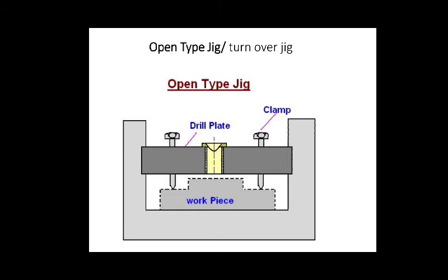This jig is also known as an open jig as the workpiece does not have any enclosure of the jig body around it, so it presents no problem in chip disposal. In the open type you can perform the drilling, and whatever chips it produces will be easy to dispose of. So there is no box over here in the open type jig.